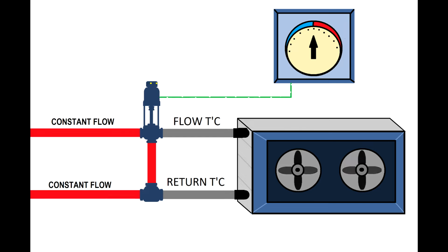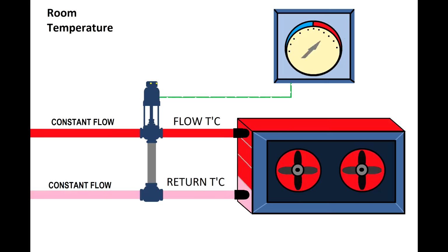To heat a building, first we have to have a heating demand, and as you'll see here, we need to set up the thermostat for a higher temperature to have a heat demand. Then the thermostat will instruct the actuator to open the three-way valve and to allow the heating agent to pass through the heat exchanger, and the fans then move the air to the heat exchanger, heating the air. This type of valve is 0 or 100%. It is not proportional, so we do not have a capacity control in this situation.